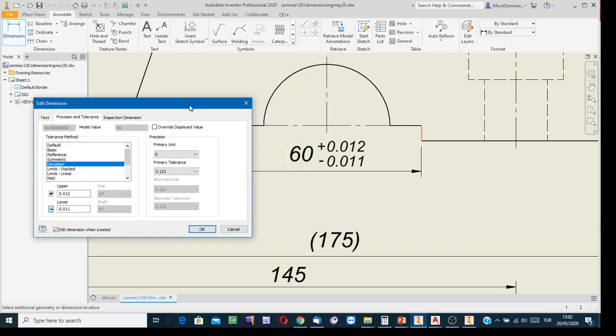Here, well, during the dimension configuration stage, you know, for non-functional dimensions, we said that deviations start from tenths, so show the nominal values as integer. So at the time we selected the precision as no precision, 0 precision, with which we had the nominal values as integer.